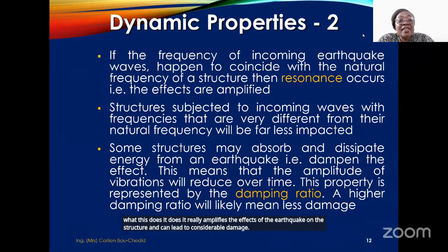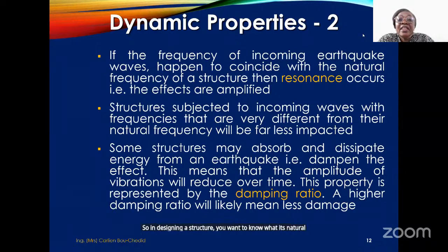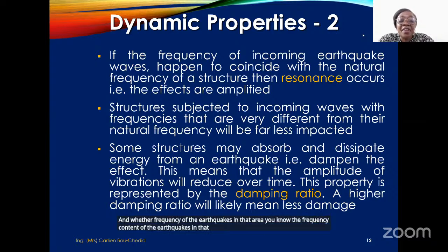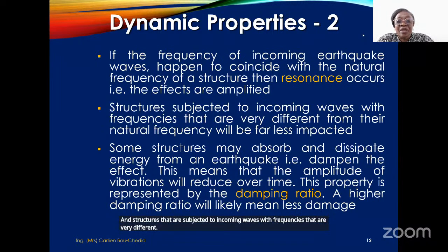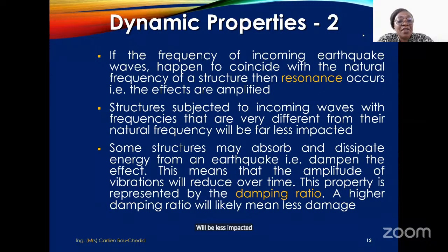So in designing a structure, you want to know its natural frequency and the frequency content of the earthquakes in that area, so you can try to design structures that will not experience resonance. Structures subjected to incoming waves with very different frequencies will be less impacted. And so that's why you do that.